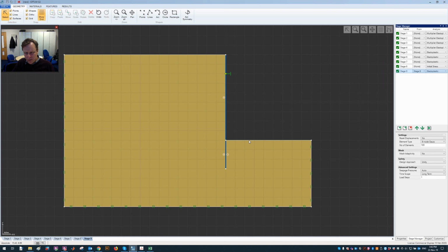But by removing this material, you of course have some residual forces. You can imagine you have some forces of a certain magnitude that keep this initially stable. Then you decrease these forces to zero, and that's basically what the load stepping does. It decreases these residual forces that are in place to make this situation equivalent to this situation. So these residual forces are decreased in the course of a number of load steps. But that's not a very physical thing to do, of course. It's a completely fictitious thing to do.